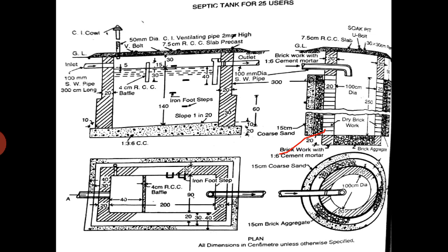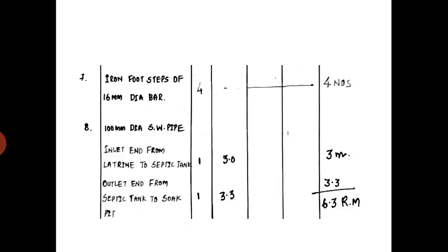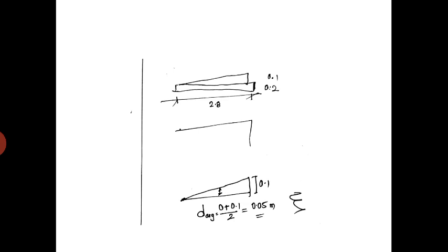When you are calculating the height of the sloped area of the cement concrete, the calculation should be done in this way. Whatever dimensions they have given in the figure are in centimeters, so that is very important. For the triangular shape, the height is 10 centimeter.